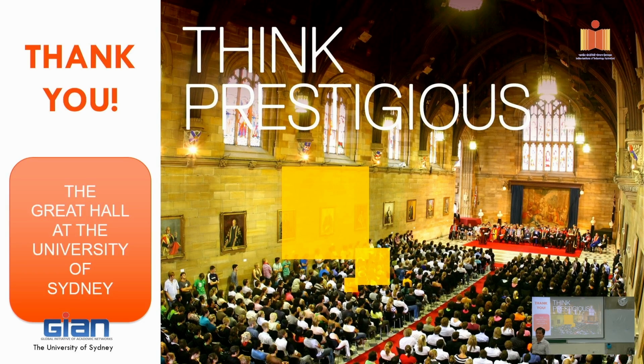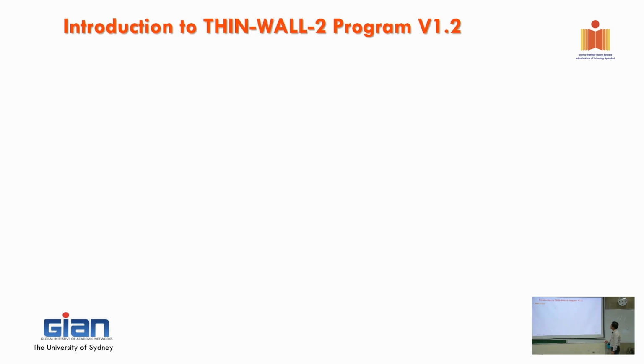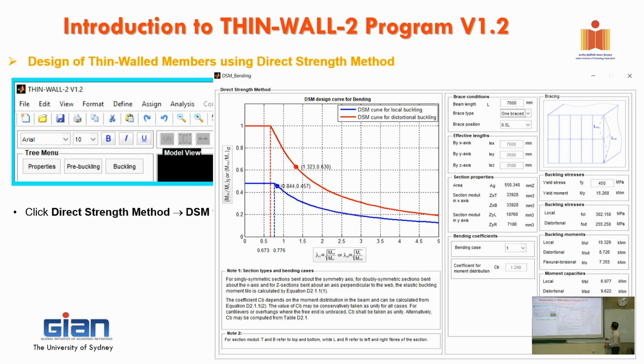Material property. Material yield stress. Okay, that's a good question. I think you can. In the design, you remember with buckling, there's nothing to do with yield stress. It's just in design. So in design here, that's where you put the yield stress. It's 450. You can put anything that you want because it's related to design. So in here, it's showing you where you input the yield stress. With buckling, you need this stability problem. It's not a material problem.